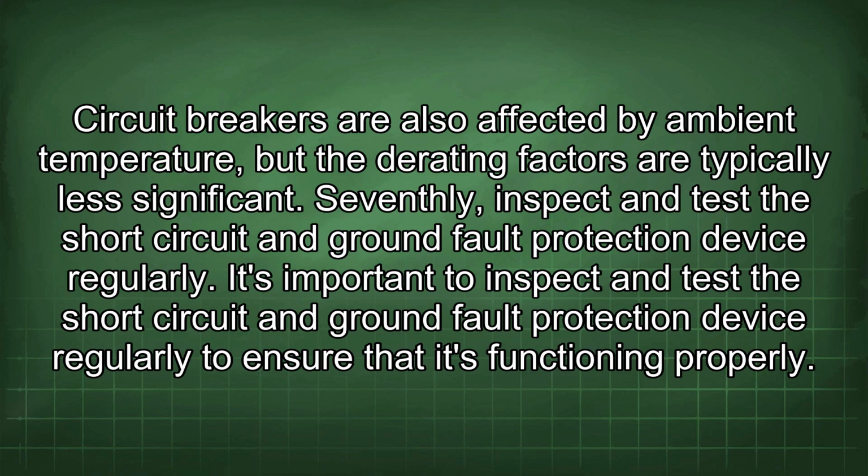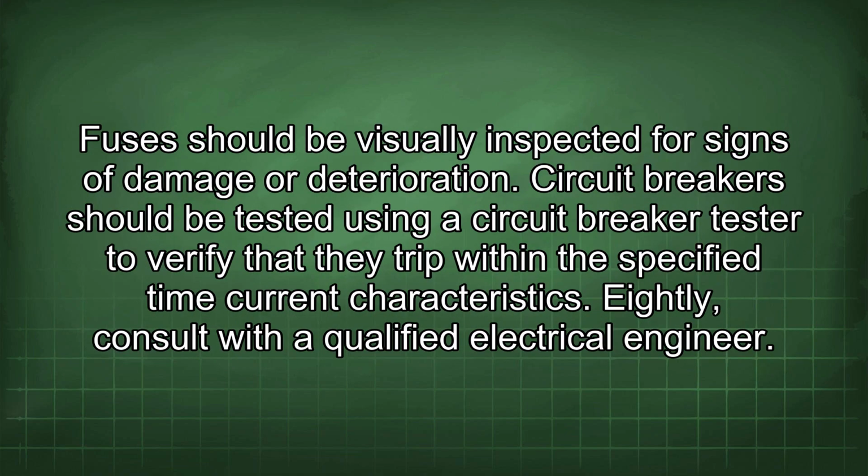Seventhly, inspect and test the short circuit and ground fault protection device regularly. It's important to inspect and test the device regularly to ensure that it's functioning properly. Fuses should be visually inspected for signs of damage or deterioration. Circuit breakers should be tested using a circuit breaker tester to verify that they trip within the specified time current characteristics.